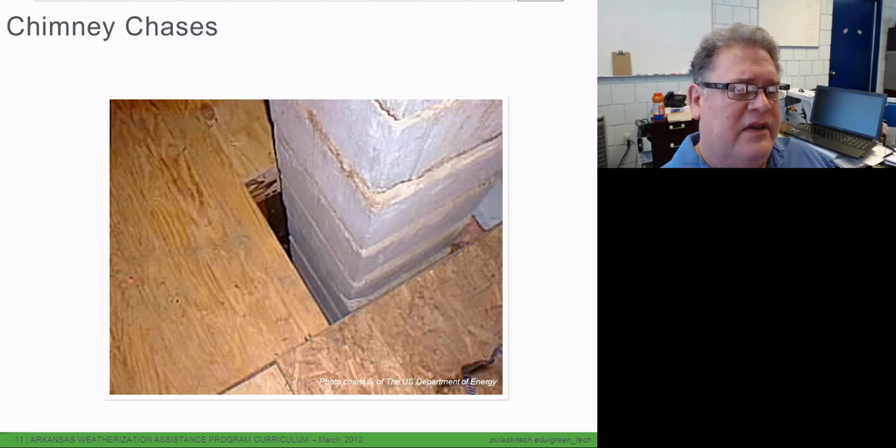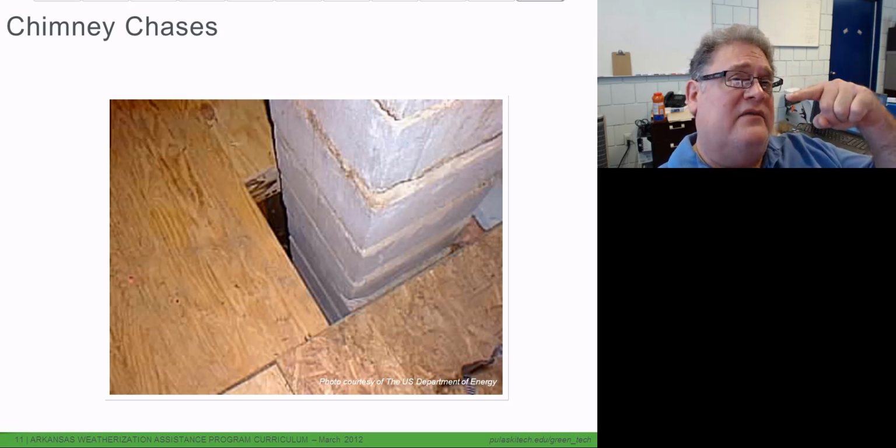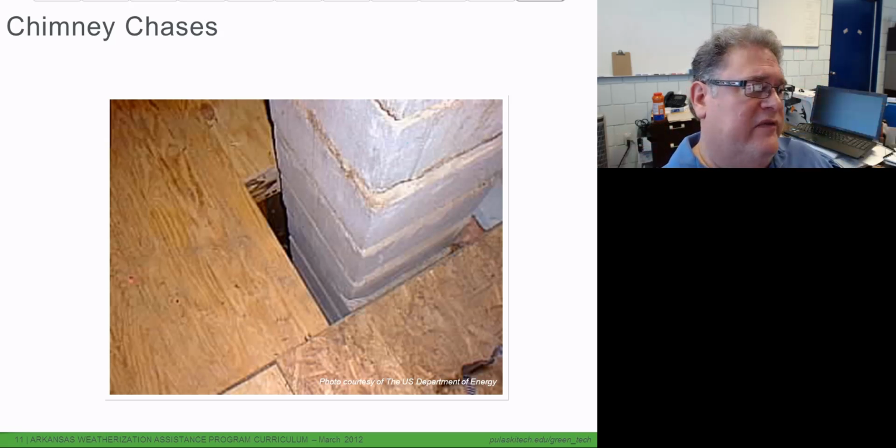The other thing that we want to look for while we're in the attic is a chimney chase. And chimneys run from the top to the bottom of the house usually. And in a multi-story building or a home with a basement in it, that's probably the tallest stack that you have in the house, which means that you've got a long way for that air to move up. And the longer the path that it has to rise, the stronger the stack effect becomes. So the faster air will move out and the faster air will move in at the bottom. So we need to block this off.